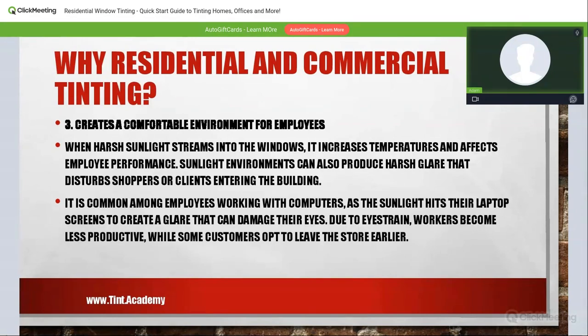Just like automotive film, there is UV protection. With residential flat glass film, there's a much higher ceramic component that reflects the UV rays from the sun. So it's going to let in that natural light while also reflecting the sun. We'll talk about this in a few more slides, but residential window tint has VLT, which is visual light transmission. It will allow sunlight in. If you go with a darker film, say a 5%, just like our automotive, it's only going to let 5% of the sunlight through.